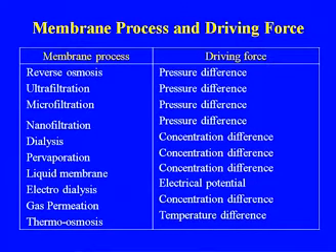Now we will be discussing the various membrane processes. As I told you, there has been continuous development in the case of the membrane process, and so now we have a large number of membrane processes where the driving forces are different. The first are reverse osmosis and ultrafiltration, which have been used from the very beginning, and here the driving force is the pressure difference. Microfiltration, nanofiltration: in all these processes the pressure difference is the driving force.